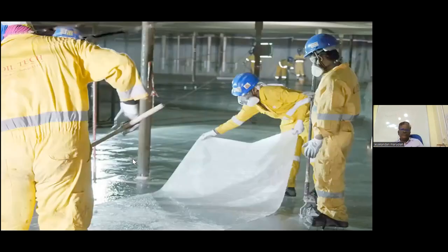The recent trend is municipalities shifting away from replacing tank bottoms and toward the application of fiberglass lining systems where recommended. Installing a lining system means applying a primer, catalyzed resin with a glass mat, tissue, and a seal coat. The tank must be dry and the surface properly prepared. The entire process is quicker and less expensive than replacing an entire tank bottom. A properly selected and applied lining can protect the steel from internal corrosion for 10 to 20 years.